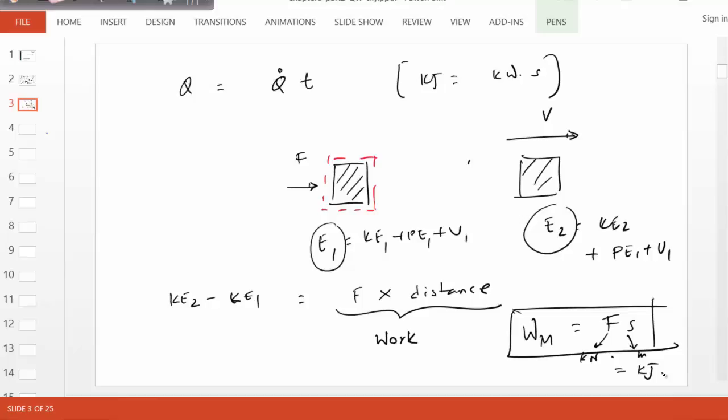So again, what is work in thermodynamics? It is energy crossing the boundary other than heat. Because if heat crosses the boundary, there is a temperature difference responsible. So work crosses the boundary whenever a force is successful in making its point of application move, and is given by this formula. Again, you know that from your background in mechanics.